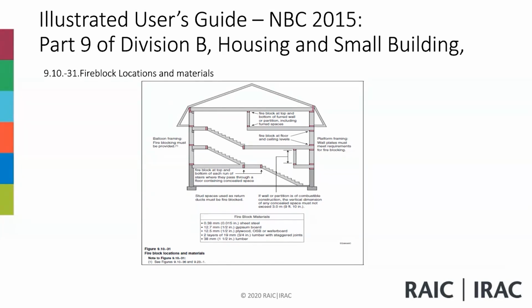So in fire separations, and fire prevention of service rooms, prevention of exterior walls. I'll get the provisions for you for the fire blocking. Okay, 9.10.16. So 9.10.16 is the provisions related to fire blocks. And as you see here, you'll see the different types of fire blocking that are used, required in different areas of the building.